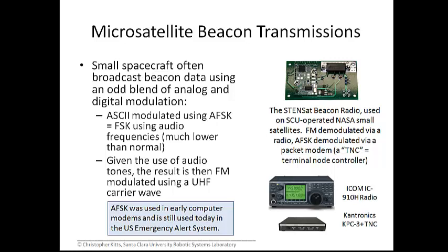And they said, well, we have digital information, so we're going to do a shift keying approach. But there's no need to shift key full-blown microwave frequency radio waves, because we're not doing satellite communications. I don't need to worry about absorption through the atmosphere. I'm trying to get these through phone lines, and phone lines are built for audio frequencies. So they frequency shift keyed audio frequencies in order to get this information to the phone line.